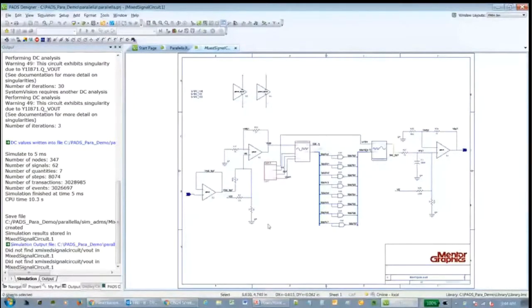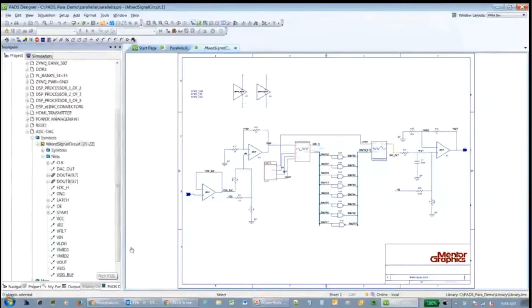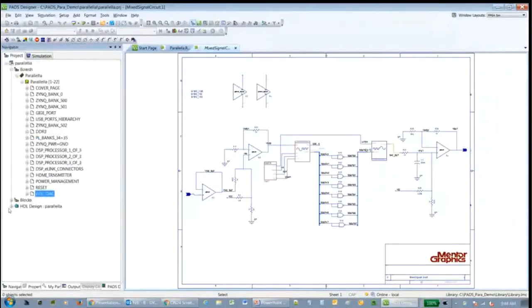Along those lines, if you're doing any FPGA stuff out there, you can also link in VHDL code to your symbols in the tool, and you can compile all of your VHDL data right from within DxDesigner, and you can launch the tool from in here.